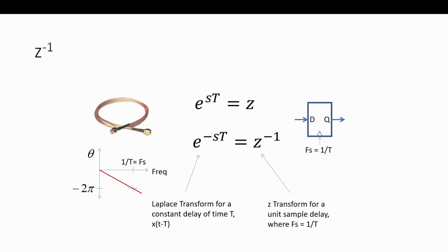So here, if we have one sample, it's z to the minus 1. So if the update rate is 1 over T, then we just get z to the minus 1 doing that same substitution, that matched Z transform that I told you about. So big point, that's z to the minus 1. And phase is really important and gets overlooked often when we look at systems because we're used to seeing a filter or something like that. Here's the magnitude response, and we don't look at phase, but it is a really important parameter to understand and keep track of. Okay, so now we're doing good.